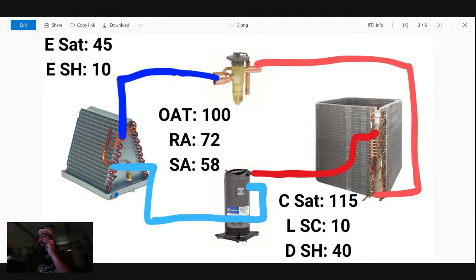There's a lot of condensation. Is the suction line sweating more than usual? If that's the case, the system is not dehumidifying. But you're saying the blower is too fast. Yep. Slow the fan down.